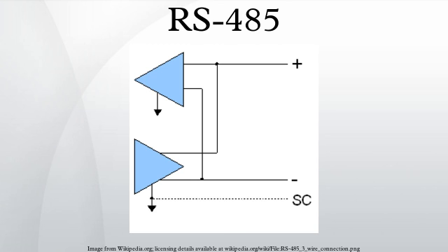Section 4 defines the electrical characteristics of the generator, receiver, transceiver, and system. These characteristics include definition of a unit load, voltage ranges, open circuit voltages, thresholds, and transient tolerance. It also defines three generator interface points: A, B, and C. The data is transmitted on A and B. C is a ground reference.